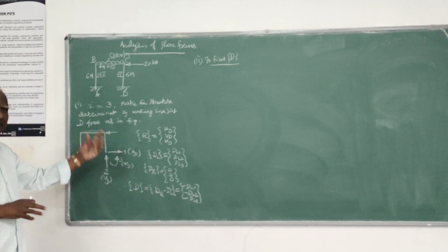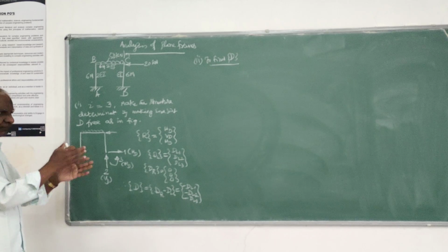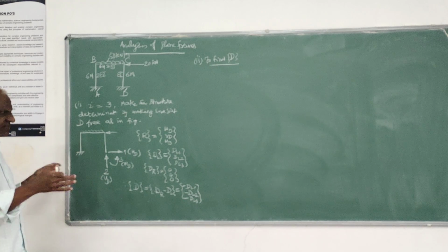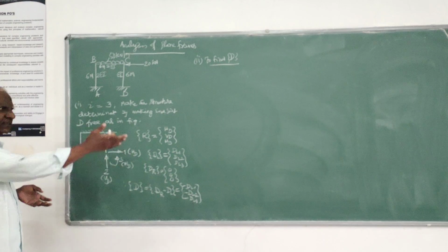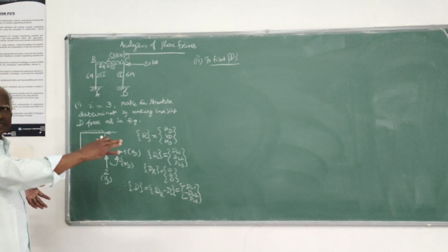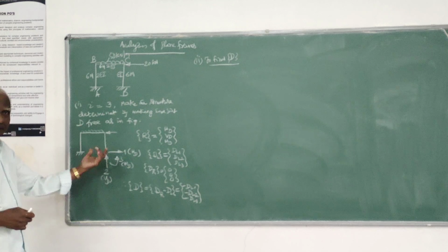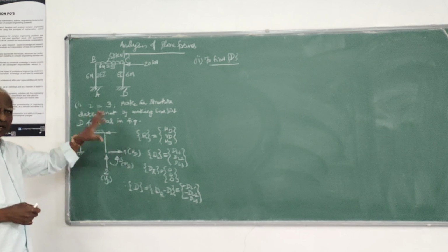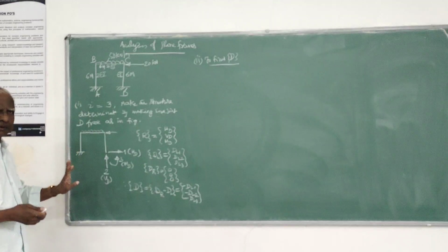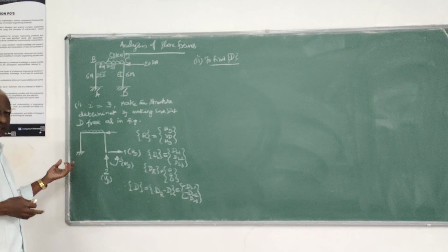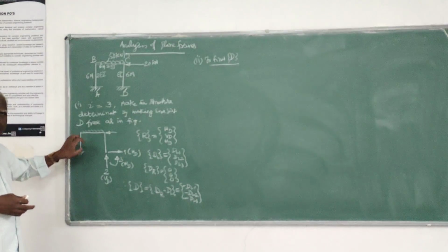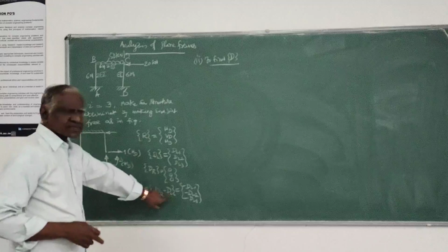Those 2 units you have to remember. First unit, finding simply supported beam displacement, using the ready-made formulae, which I already used in the analysis. Next, the strain energy method, evaluating the displacement by applying Castigliano's theorem. So that we are using here now for finding this DL.